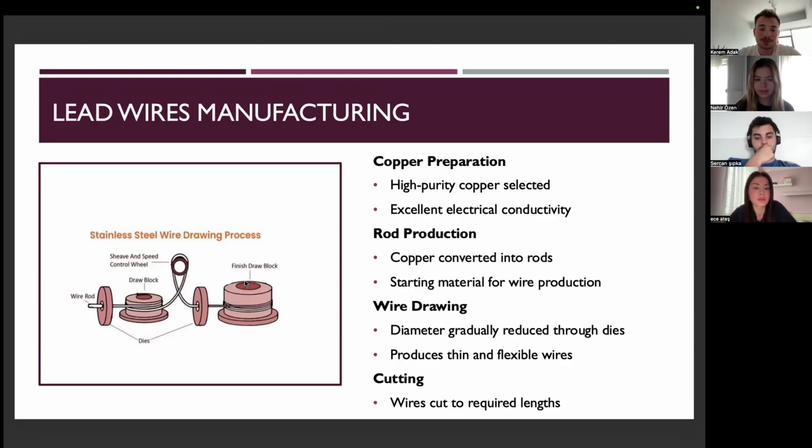The final topic is the soldering operation. Soldering is used to connect the lead wires, the filament system, and the base. This process is very important because it completes the electrical circuit inside the bulb. The first step is positioning. All components are carefully placed into the correct positions before soldering starts. Correct positioning is important for reliable electrical connections.